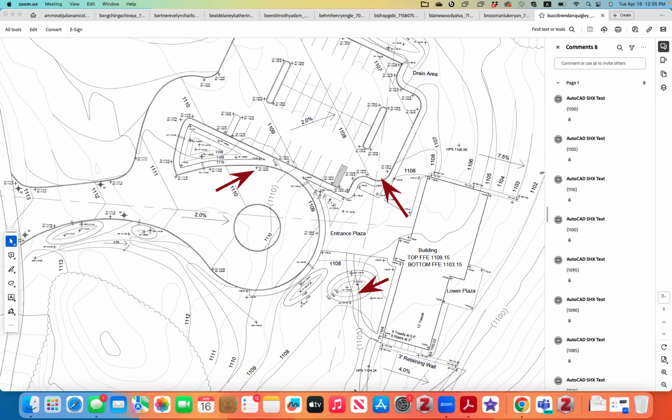I would basically reshape the swale so that the shape is more pronounced for the swale. And also the tip of the swale is to go beyond the edge of the retention. I would cut this down, okay, so that I make more room here for my swale.